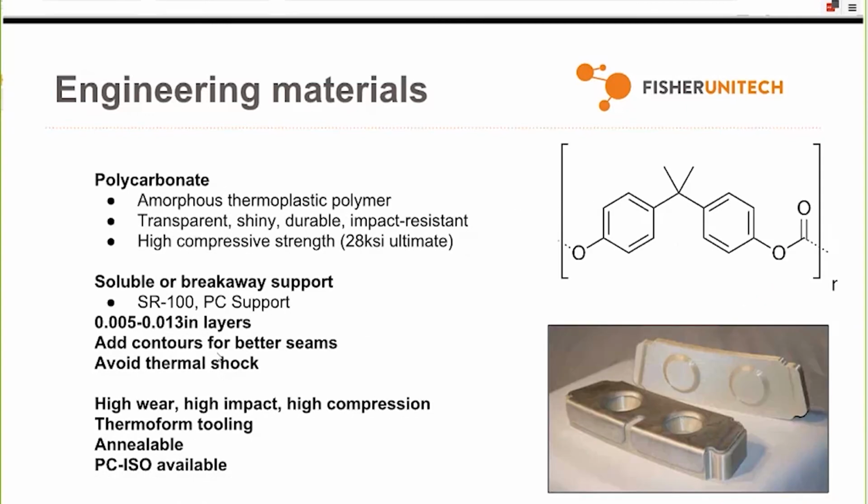Polycarbonate. Now, this is better known by the SABIC trade name Lexan, and it's basically repeating long chains of this basic carbonate molecule over there, and those tangle up when it hardens, like other amorphous polymers do. It's naturally a transparent resin, though Stratasys only sells it in an opaque white color. Now, PC is way more impact resistant than ABS, as long as parts are undamaged. So I'll explain a little bit what I mean. If you're looking at the material spec sheet, this will make a little bit more sense.